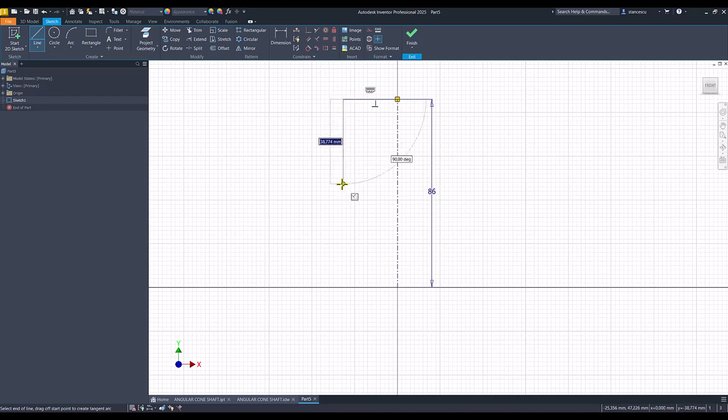If you are very careful, I press the left button and I draw an arc. I press the left button and I draw another arc. Then a line, tangent, as you can see. Tangent. Then I go to horizontal, not perpendicular, here, and back to the center point.